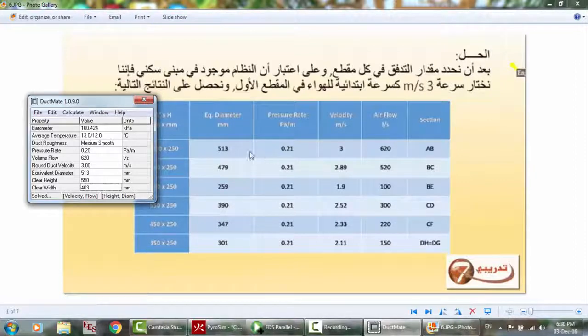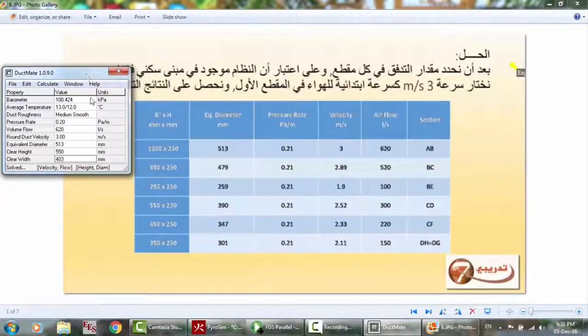And look at this, 250. Okay, just about 982, but we did not find this in the standards, so we got the larger, 1000. Okay, then this will be the same. Equal friction method tells you that, and then we will change this.